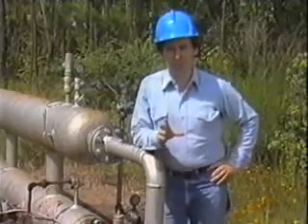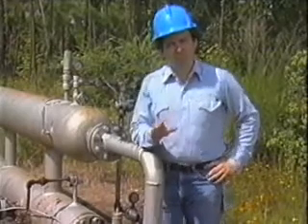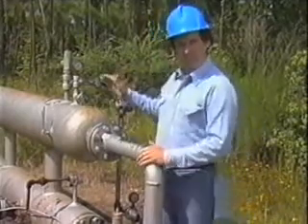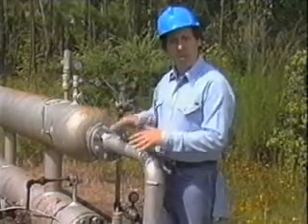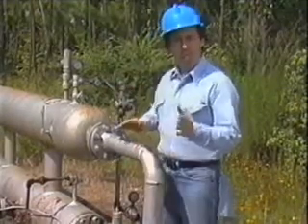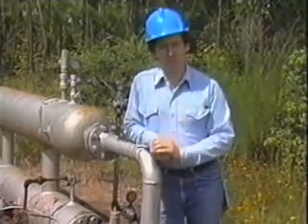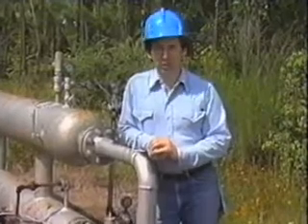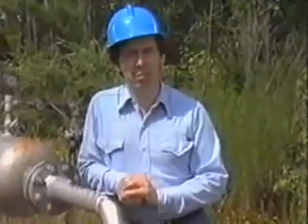Two-tube separators can also function as three-phase separators. In this case, gas exits from the upper cylinder. Oil exits from the top of the lower cylinder, and water, being heavier than oil, exits from the bottom of the lower cylinder. All right, I told you earlier that production separators can also be spherical in shape.